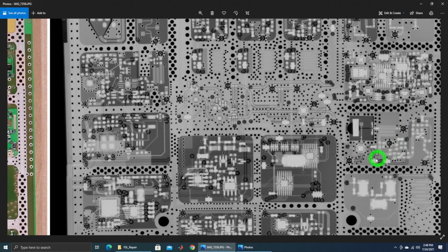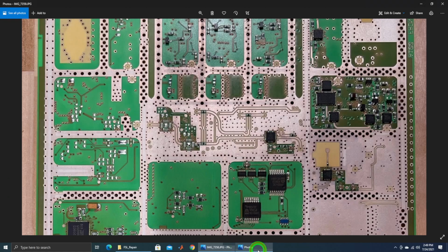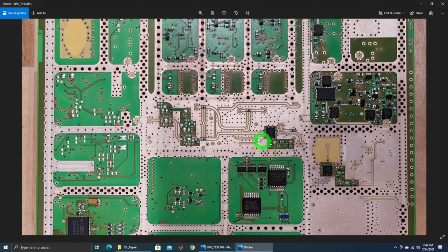quite unusual. We have the LO, I believe, coming over here, and there's this amplifier here. This is a 6 to 13 gigahertz amplifier. So if I go to the other side of the board, that's the section. Look at that. So the signal comes over here, amplified, and goes into this feed line. And this feed line is basically almost like a probe feed into the substrate. So it's transmitting into the substrate.